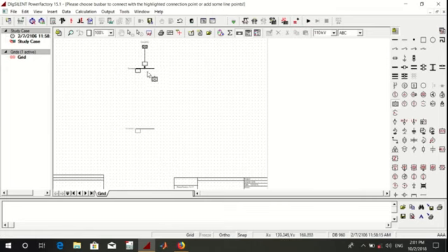here. From the grid it is fed to the bus bar. Next, click escape, go connect two bus bars by a line, transmission line, two bus bars. Okay, it's connected. Then escape, go and select a load. This is the load connected.